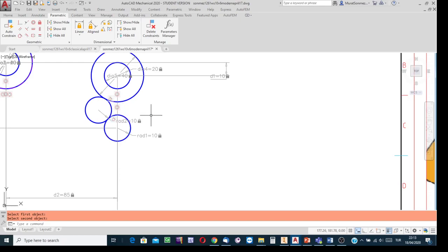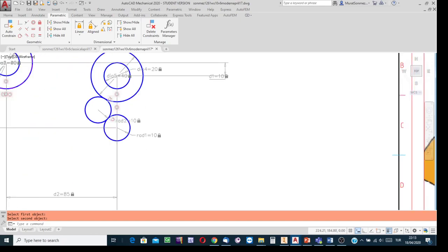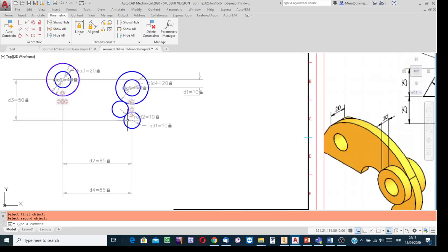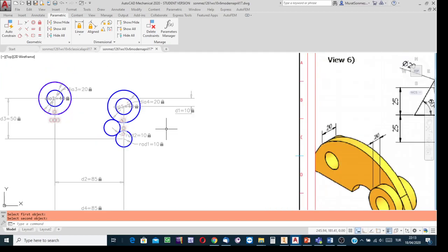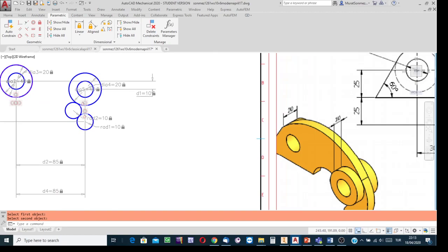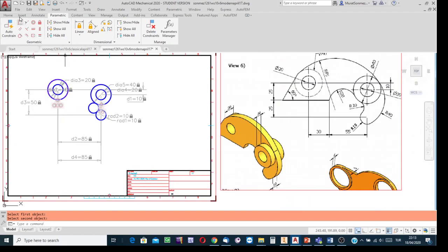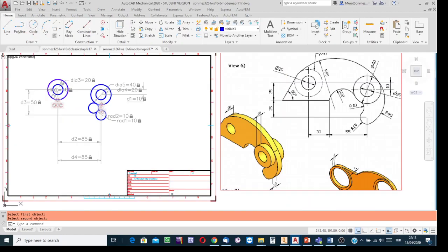Be aware, the software is AutoCAD, an old generation software, and trimming is not allowed at an intermediate stage, because if you trim this circle at that stage, then the associated constraints will also be trimmed, deleted. And at the next stage, you may find the already drafted one as if exploded, because they lost their constraints. So do not apply the trimming process. Continue.